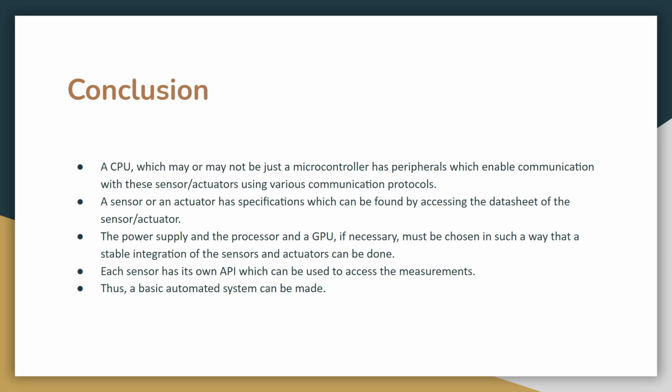Another very important topic, which I myself am pursuing my career in, is robot motion planning. Motion planning of robots combines path planning of a robot from an initial state to the goal state, and trajectory planning, that is finding the velocity, the acceleration, and all those kinematic and dynamic parameters, and planning the values for those parameters for the motion of the robot, for every degree of freedom, every joint and every link of the robot. And the last very important domain of robotics is control systems.